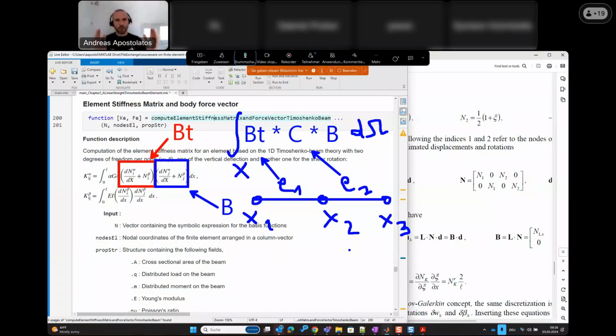They're just continuous within each element. And we can only perform numerical integration on domains where the basis functions are actually C infinity continuous. If they are less than C infinity continuous, we cannot perform integration. That's the answer here. Is there any question on the construction of the B operator matrix and why we integrate it along each element? Is there something that you would like to know more?